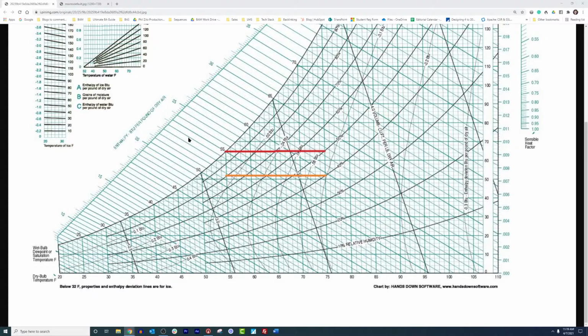And just remember, dew point lockout and enthalpy lockout are going to basically be the same thing, although they're different numbers. They're affected by the same thing, right? We see dew point, and the thing with dew point that you have to realize, this is the last thing I'm going to add, is that dew point may be at saturation and cause condensation inside your equipment.